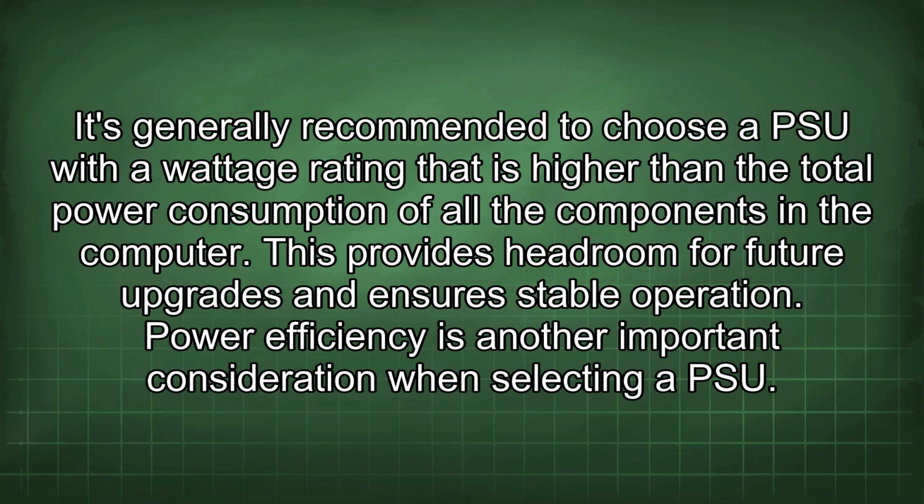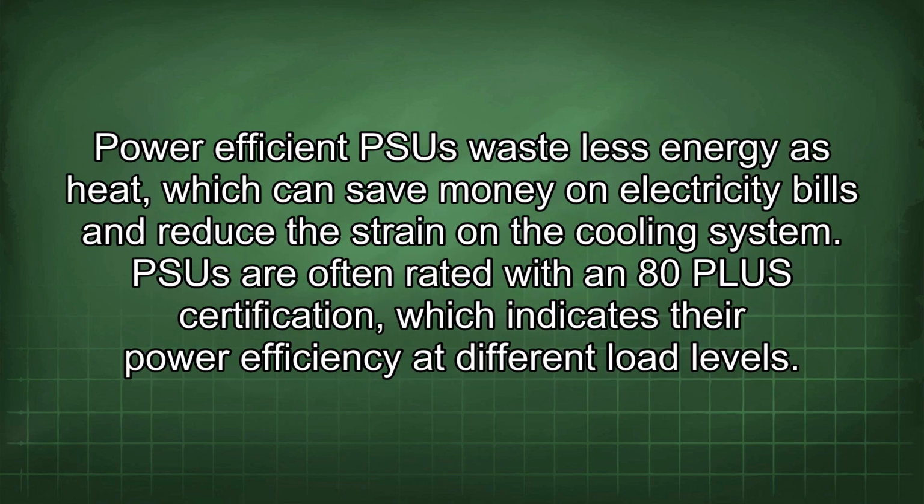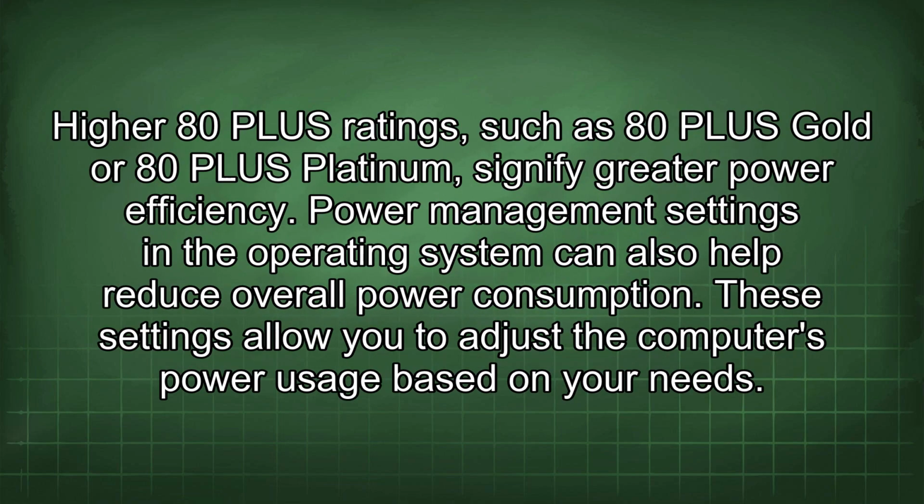Power efficiency is another important consideration when selecting a PSU. Power-efficient PSUs waste less energy as heat, which can save money on electricity bills and reduce the strain on the cooling system. PSUs are often rated with an 80+ certification, which indicates the power efficiency at different load levels. Higher 80+ ratings, such as 80+ Gold or 80+ Platinum, signify greater power efficiency.